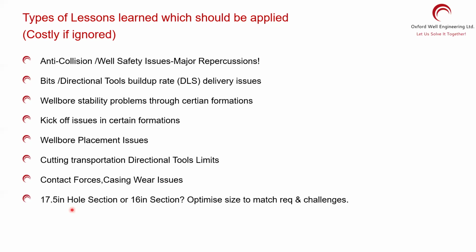Do you need to drill 17.5-inch or 16-inch? 16-inch is easier to build angle compared to 17.5-inch, but there is a reason why you want to have 17.5-inch. Sometimes it's difficult to run casing in 16-inch. 17.5-inch could be a better option. So we need to weigh these pros and cons for everything. Difficulties running wireline: if you must run wireline and you cannot run it, there's no point drilling.